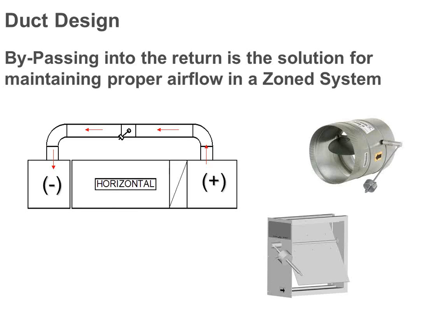So we have to have a way to relieve that pressure, and the way we do that is typically with a bypass damper. We could also do it with a dump zone, but that requires having a room in your house that you don't care about, which most people don't have anymore. Ideally, the takeoff for the bypass damper should be upstream of the zone damper takeoffs, right? That would be the most ideal scenario.